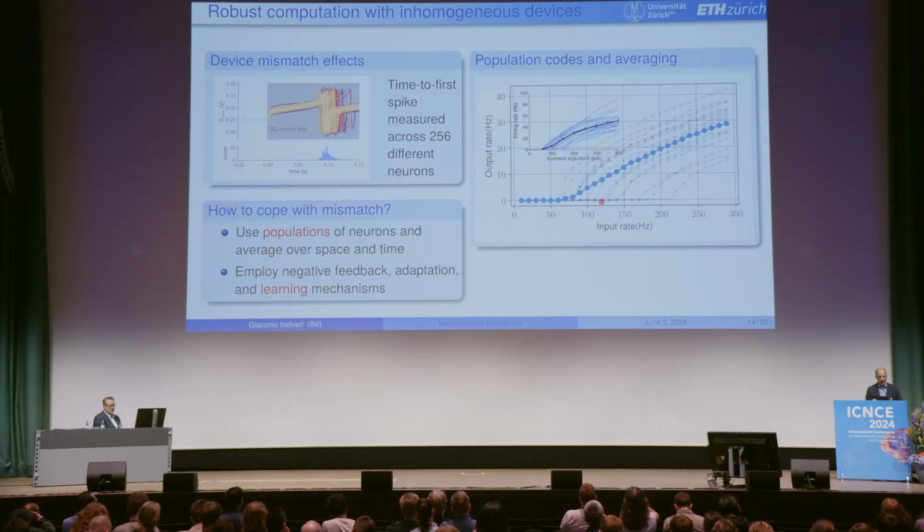If we stimulate them now, not with a simple current, but with spikes in input through the synapse, which then gets integrated by the soma, and then the soma produces spikes in output, the frequency to frequency plot, FF curve, is shown here. And you can see the gray plots here are all the single neuron responses, and they're all over the place. It's this, as I told you, 20% coefficient of variation. But if you take the average over these 256 neurons, you see this very nice ReLU curve, which is very, very accurate.